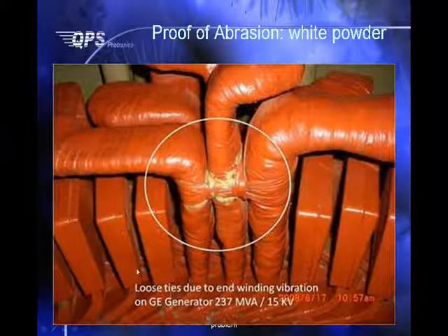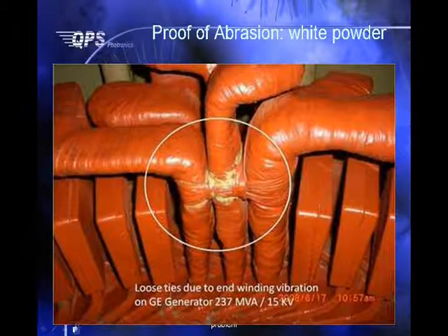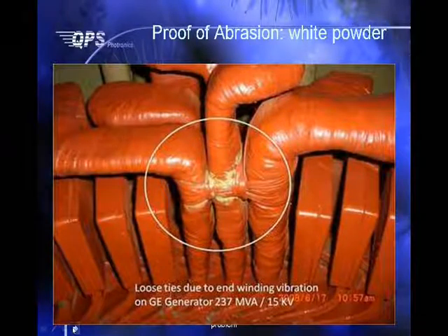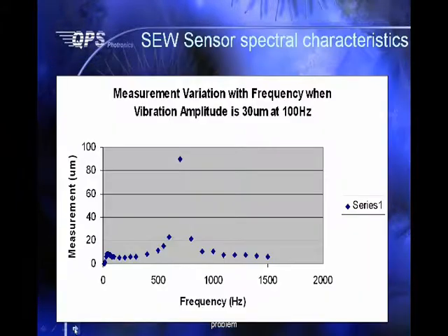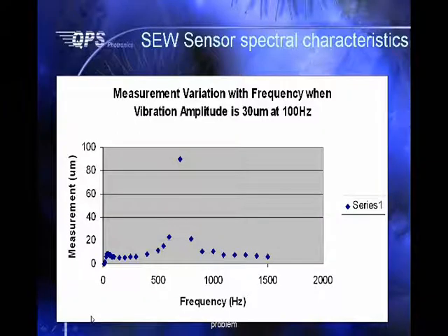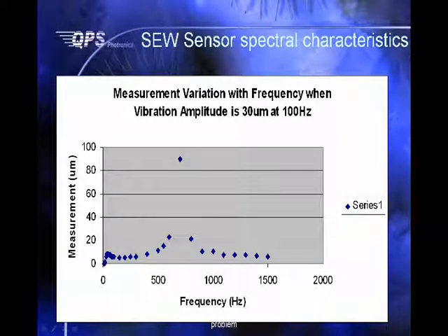And so what we hope to do is introduce you to a concept of much earlier detection, and that is by trending the vibration amplitude. We agree that the vibration is always there. We further agree that looseness enhances its amplitude, which introduces rubbing, and now we will explain to you the details of how we solve this problem.